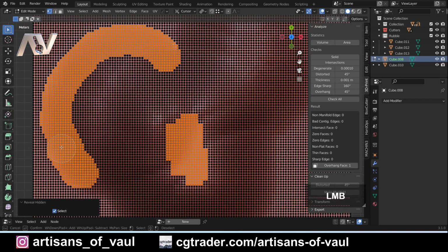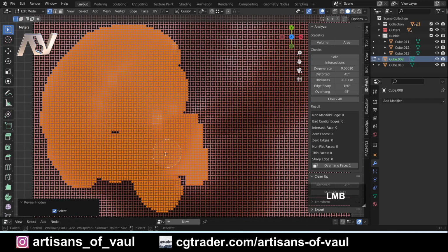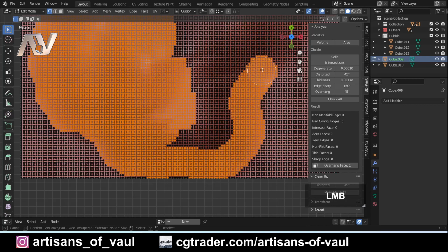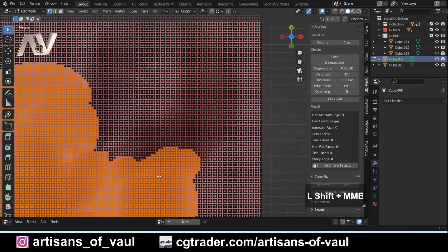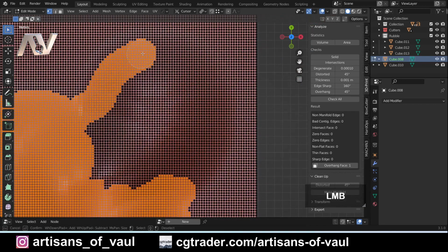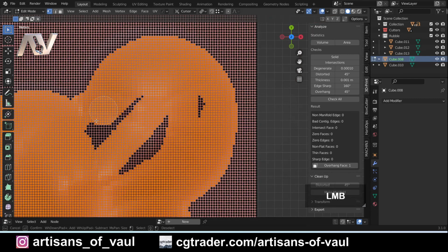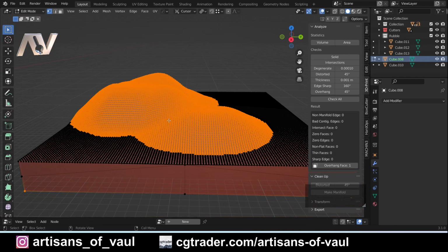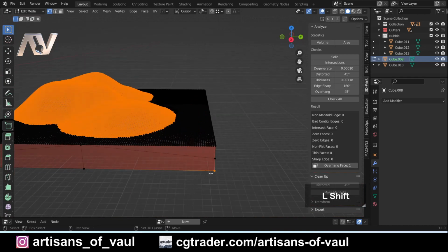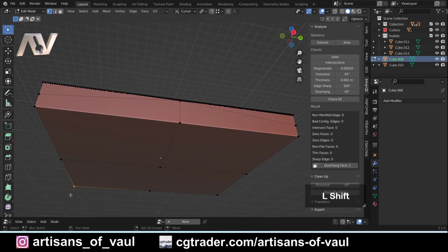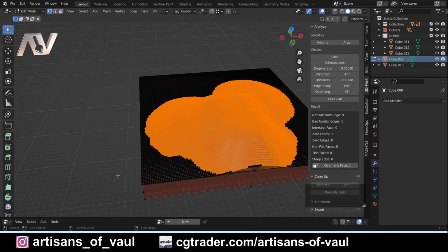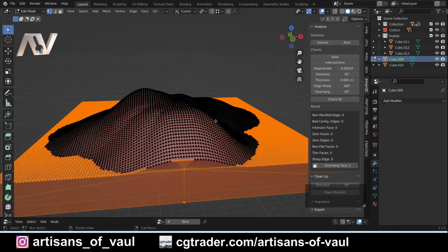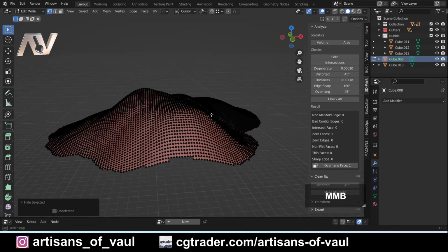I'm going to press C for circle select, and I'm going to select those ones that we want again, so the ones that are actually raised up. Come to think of it, this would probably be slightly quicker in lasso mode, but oh well, it's done now. Okay, and then all I'm going to do is press Control. Oh, I've still got some of those selected, so I need to unselect those and those. There we go. And then I'm going to press Control and I to invert those, and I'm going to press H to hide those selected ones.